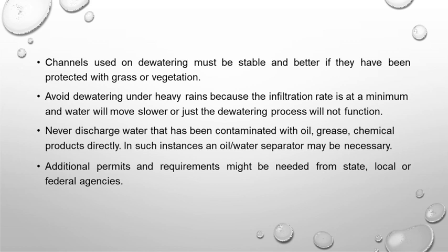So, some of the factors affecting the selection of a pump. The factors to be considered during the selection of a pump for a construction project or for construction work. First one is dependability. Next, availability of spare parts and repair and maintenance of the pumps. Repair and maintenance should be done easily. Next, less installation and operation cost, and it should be power efficient, that is, less power consumption. This point should be considered during selection of a pump for the construction project.